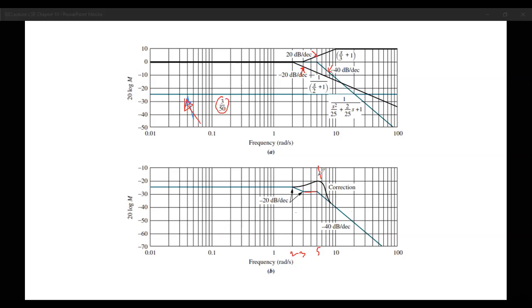So we also have to be careful about the correction factor here, which is 20 log twice zeta. Whatever equation was given to us, from that equation we have to find out the value of zeta. The equation that was given to us was s square plus 2s plus, I think, 25. Okay, so twice zeta omega n equals 2, and you know omega n equals 5, so you can easily find the value of zeta, then add the correction factor, and then rearrange your simulation, the drawing.